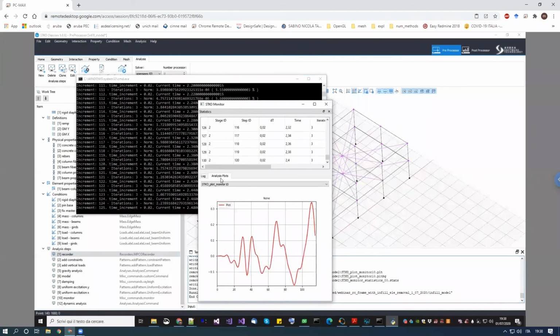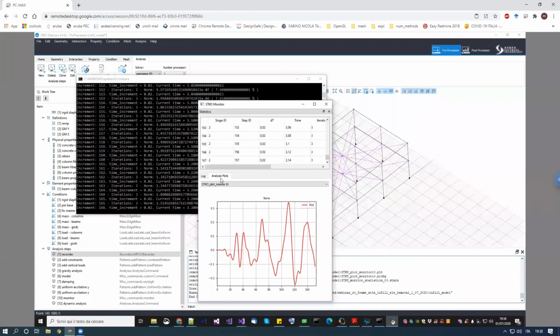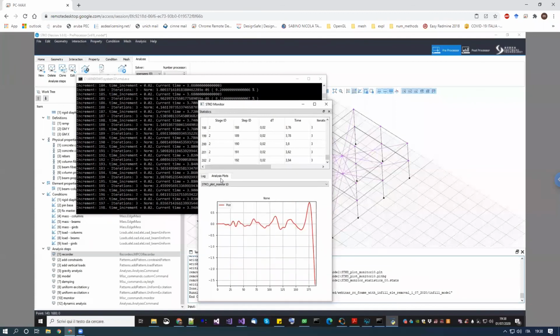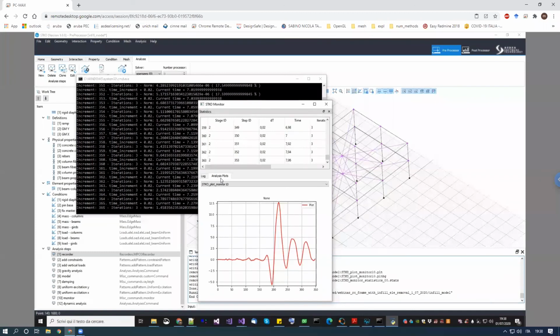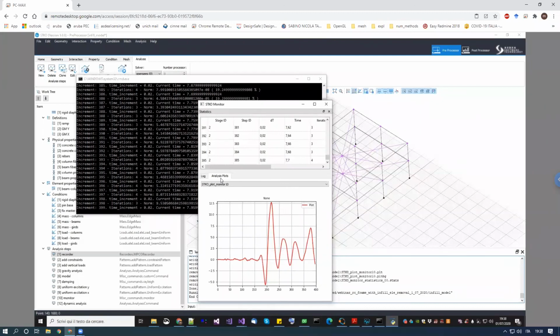In the meantime, there is another question by Nizar. It means that we can't model mortar in shell? Of course, you can model mortar in shell elements. I'm just saying that if you want to model a shell which has some kind of infill along the thickness, you can do it. But if you expect this infill to be completely different and you expect a shear deformation between the two layers of shell, that cannot be modeled with shell, okay?